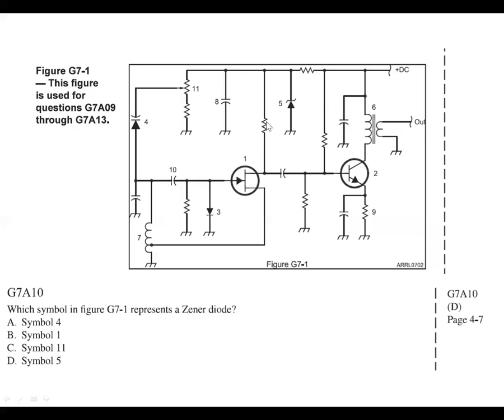And what a Zener diode does is, if you reverse bias it, it won't pass current until you reach what's called the Zener voltage, and then it'll pass current to maintain that Zener voltage. So let's say this is a 7-volt Zener, and we're providing, say, 8 volts here. What you'll have here then is 7 volts, because if this voltage tries to go higher, the Zener diode will pass the current and bring the voltage down to its Zener level.